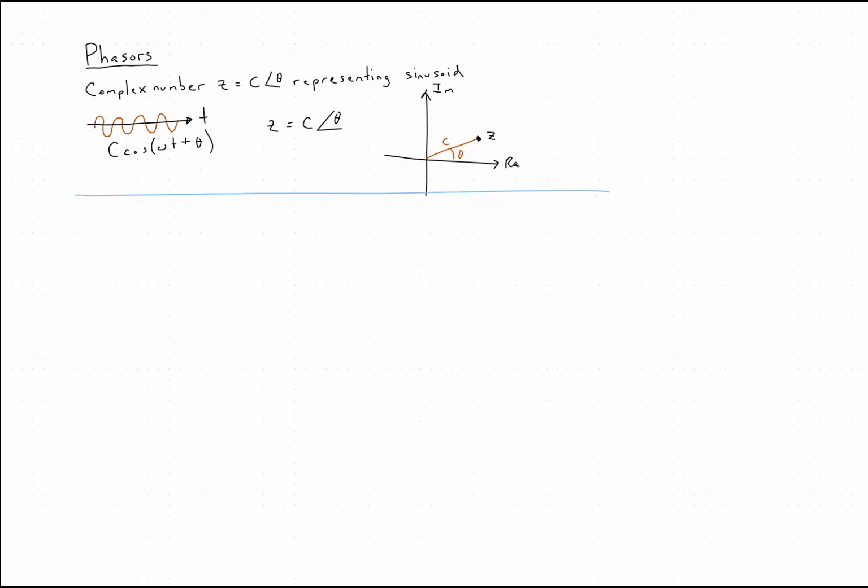Now, last class we learned how to use it to solve simple circuits problems involving only resistors. Here's an example. The problem is to determine the voltage across the current source in this sinusoidal steady state circuit. And by sinusoidal steady state, we mean that all the sources are sinusoids of some type, and steady state means that they've been doing their thing forever. There are no switches in this. The sinusoids aren't being turned on by being multiplied by unit step functions. They're just pure cosines, perhaps at an angle, and pure sines, perhaps at an angle.